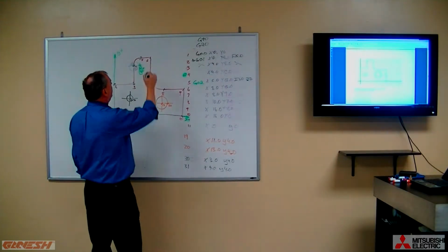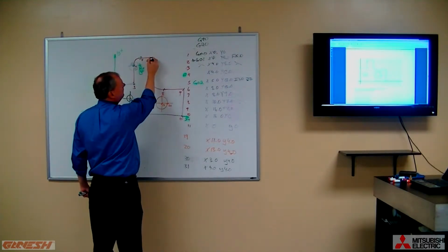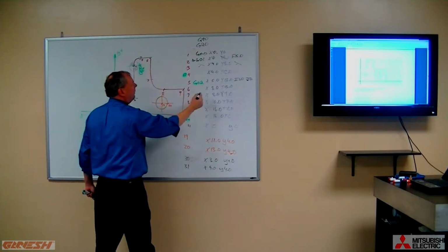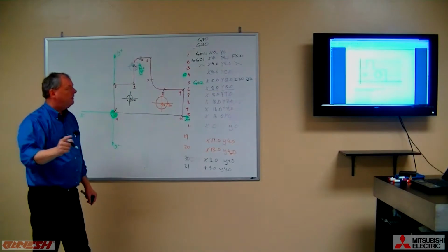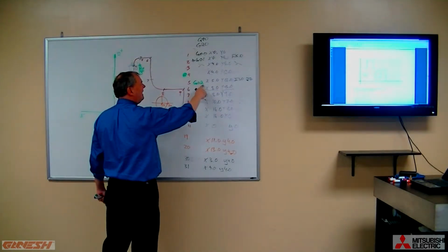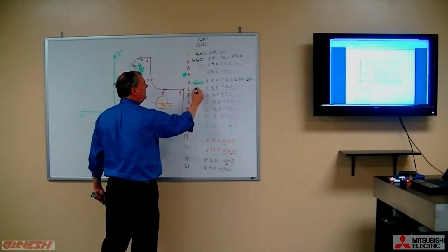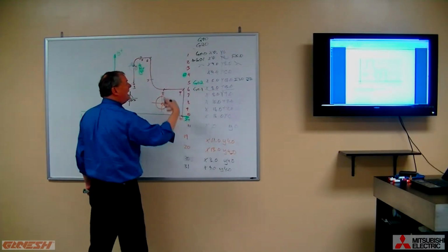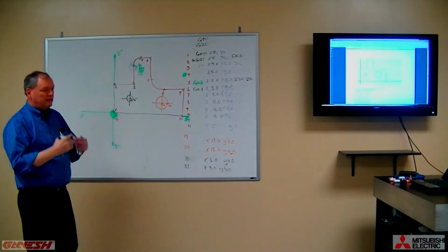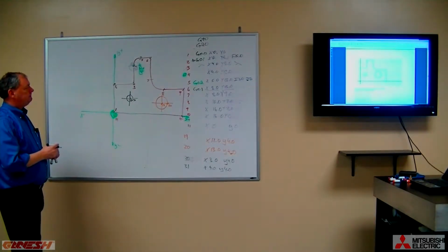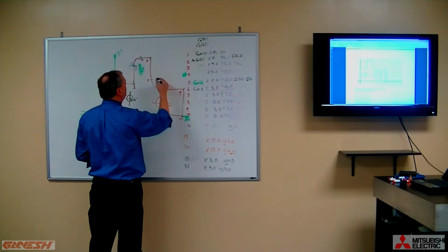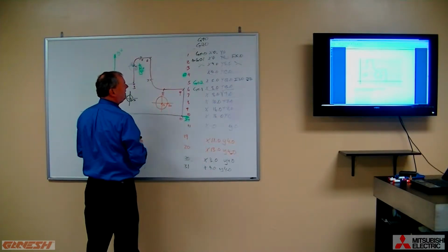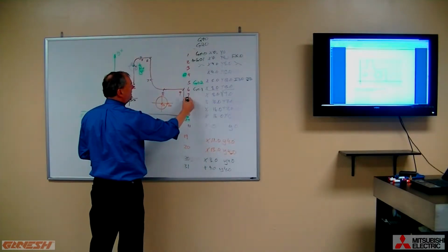Now what do I need to say to make a straight line move to get to point number 6? Well, I need to provide the X and Y coordinates. You remember? We have to cancel out this circular move, so we would now say G01 again to put it back into linear interpolation. So now it's sitting here. Now our next move goes to point number 7, and we're sitting at point number 7.